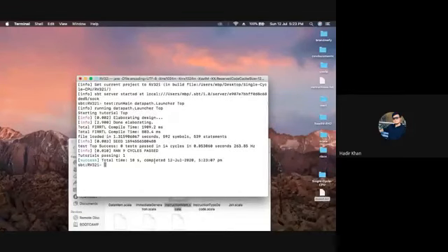All right, so it's a success. And then we'll use the same instruction, and then pass in --backend-name verilator. So what it does is, by using this, we create the Verilog files as well. The Chisel program that is written, we create the Verilog file of it, and then we generate a VCD file, which is then visualized by GTKWave, so that we can see what's happening in the processor.